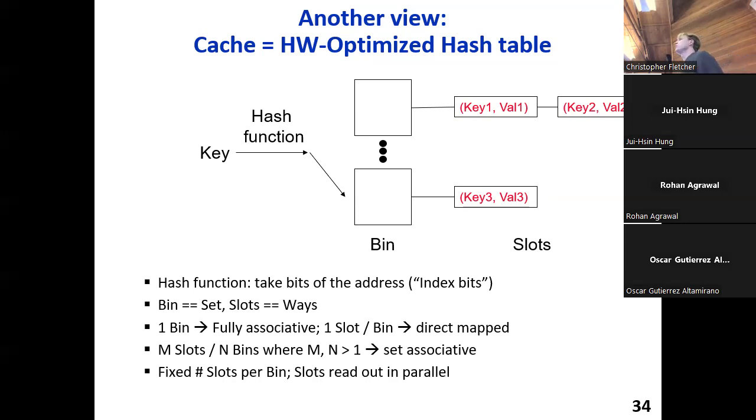To be optimal or more hardware friendly, we bound the number of slots per bin. If we had load imbalance where one bin could contain an infinitely large number of slots, and I were to stick you on a desert island and say, implement a hardware structure that implemented this, you'd be sad, because that is not easy to implement in hardware. You'd much rather just take a table like an SRAM array, which has a fixed capacity, and implement your cache out of that, which means that your bins are going to have a limited number of slots.